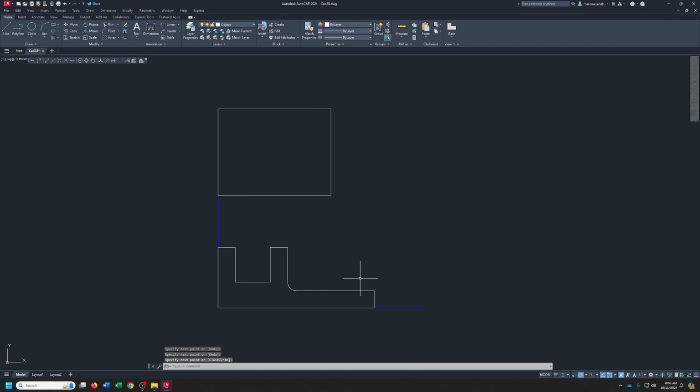Now we got that rounded front that comes out here. So just use your arc. Center, start, and end. Pick the midpoint of the line, go down to the bottom, and swing that arc across the top. Leave that line there. We're going to need it in a minute.